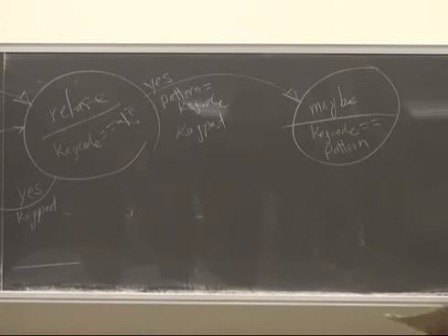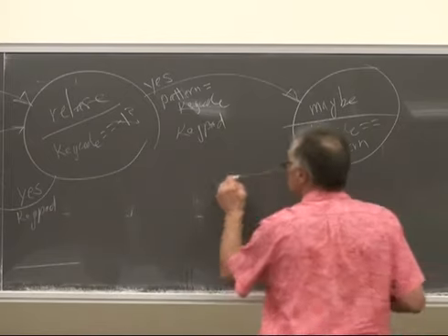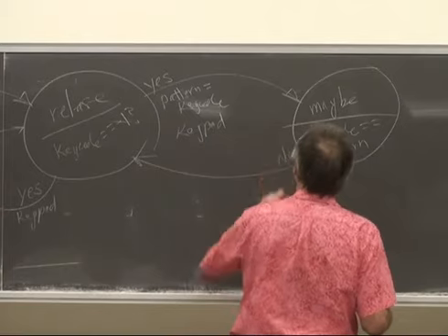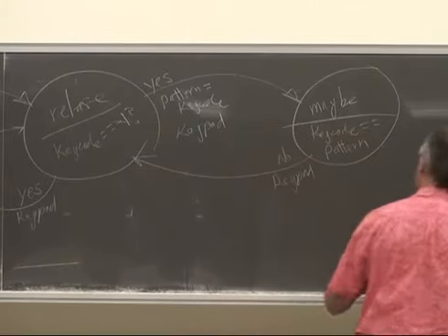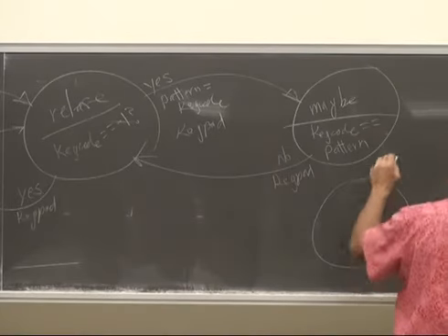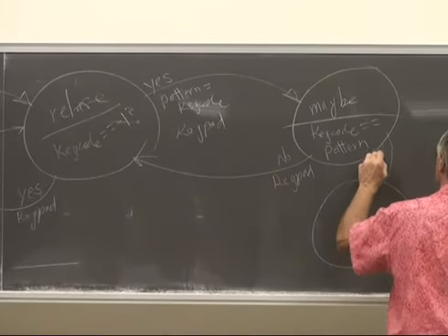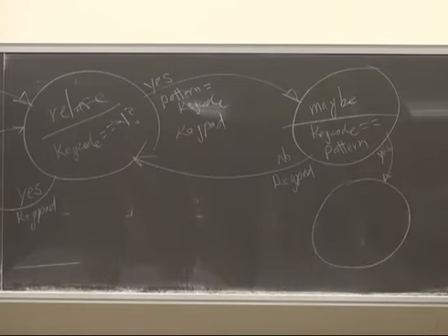If the answer is no, where do we go? Back. No, and we call keypad again. The answer is yes. At this point, we know we have a valid key push. It's been pushed twice in a row at 30 millisecond intervals. We know we have a valid key press.